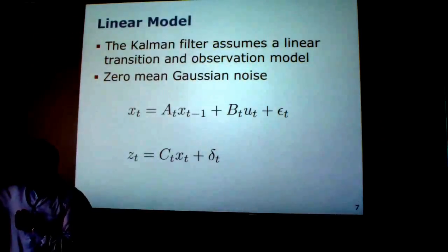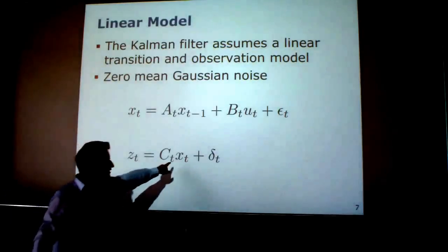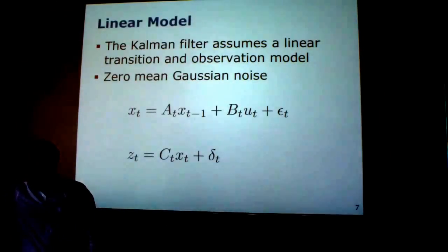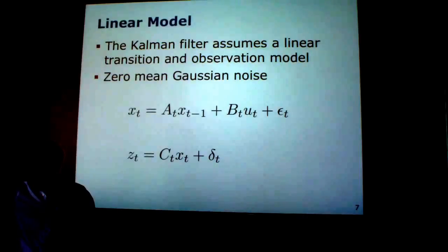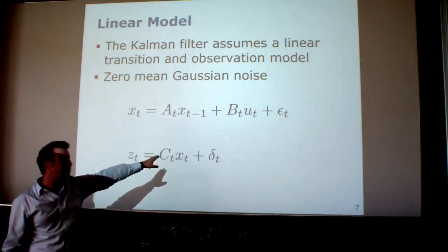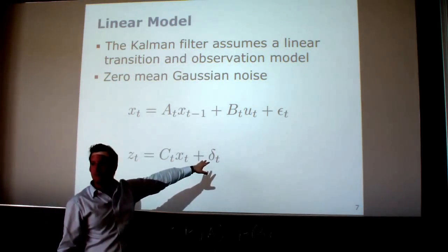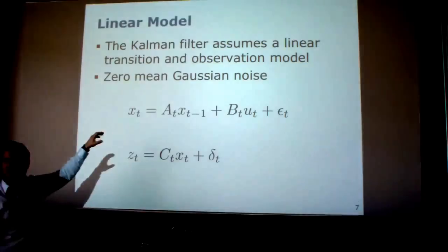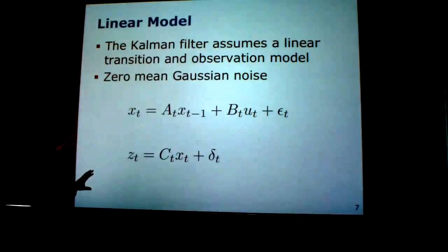So given my state tells me the robot is here and there's a feature 1 meter to my right-hand side, I need to be able to predict this 1 meter expected observation based on the linear function, which has to be done with this matrix C_t, plus some Gaussian noise. These are the assumptions that everything is a linear model, which we have in the Kalman filter.